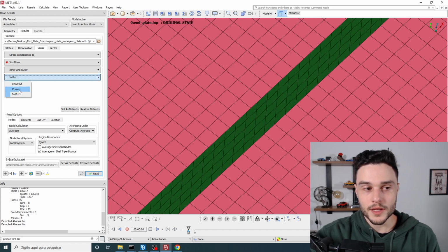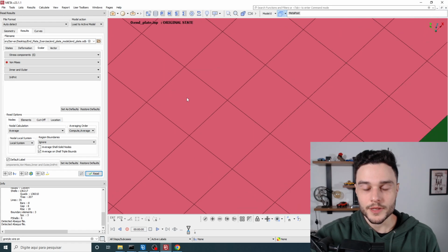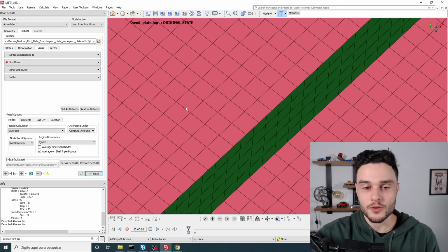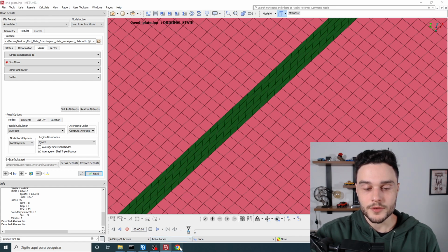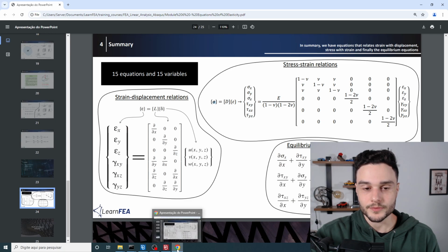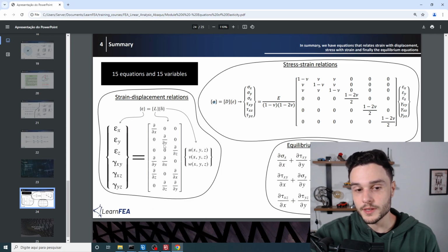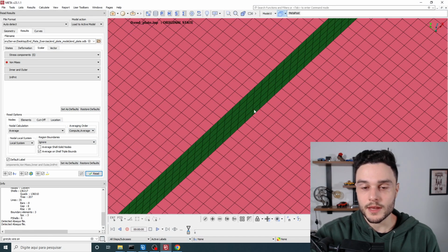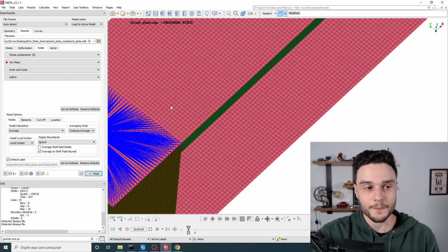We can also calculate on the corners, that is at the nodes, or on the centroid. But on the centroid is not really a good option, because then we would have only one stress being calculated at the centroid of the element. So we would have fewer stress points being calculated by using these expressions that we have here. Okay, not exactly these expressions, because as I mentioned, here we have finite strain, not infinitesimal strain. So integration point.